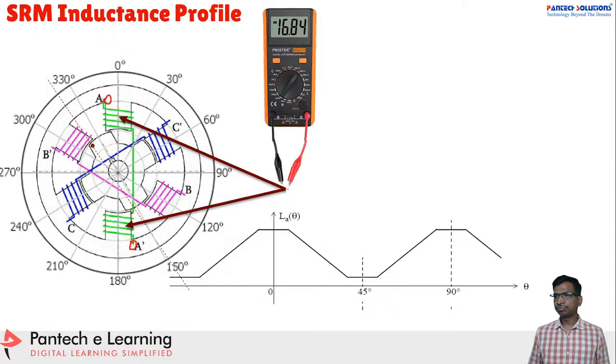That is how we will calculate the SRM motor inductance profile. I will share special notes and an image of that position, how to draw it and how to fix your motor, after some time. Now see how to calculate this value. Use this LCR meter, connect it across the winding, and then change the rotor, and you may get a value like this.